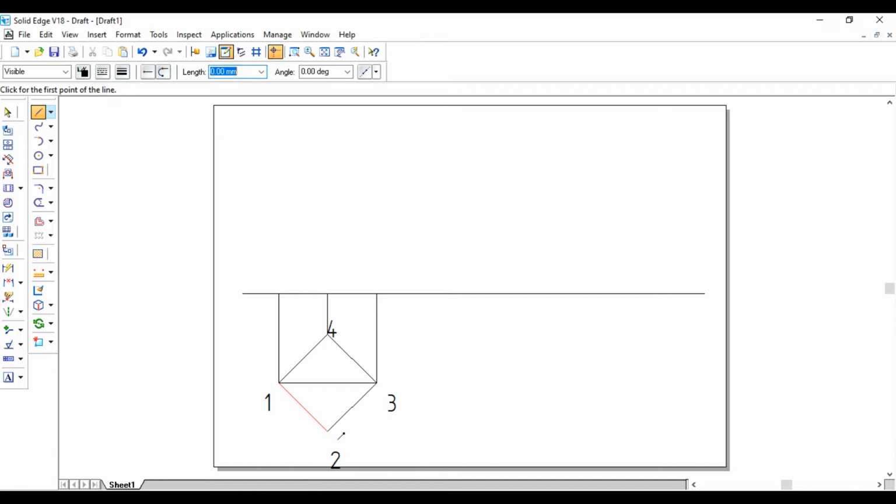Okay, so locate the center. I'm going to locate the center. So this one will be O. Okay, next, the height is 65 mm. Therefore I'm going to draw a line from this corner of length 65 mm. Enter. From there I am going to draw a horizontal line like this, and I am going to end it. And this is the other vertical edge, it will be visible.